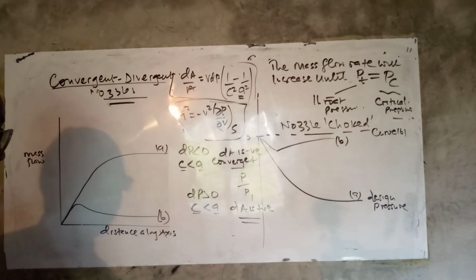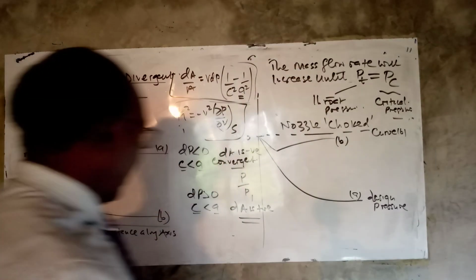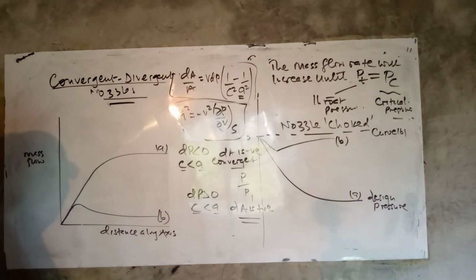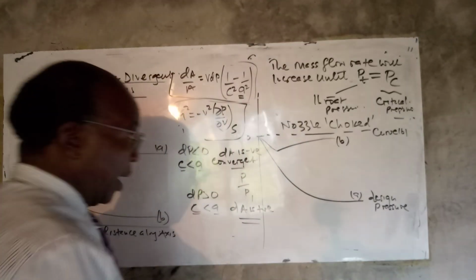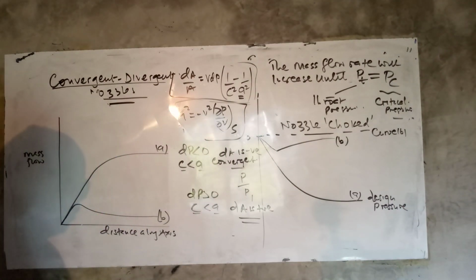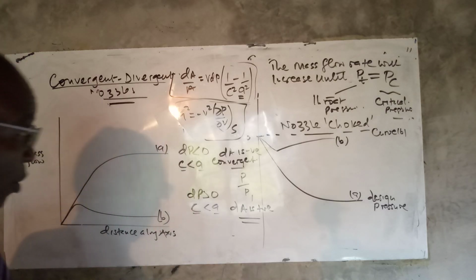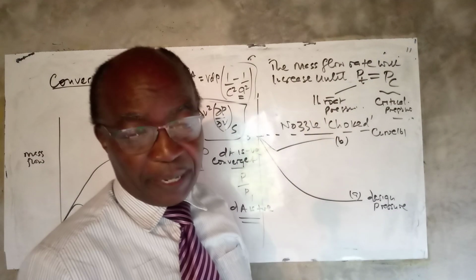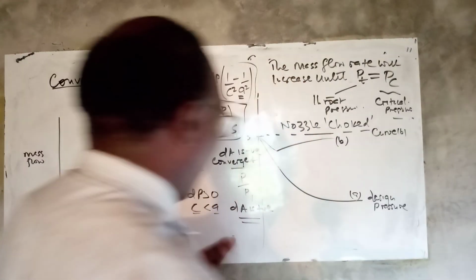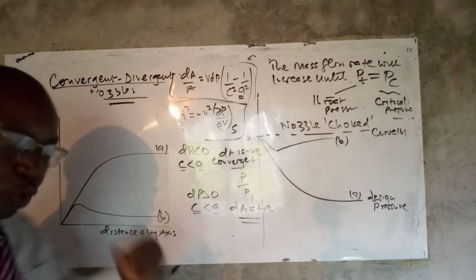Now, suppose we continue lowering the pressure, the downstream pressure. Of course, what will happen? Remember, once the throat pressure is equal to the critical pressure, there will be no change. So the nozzle is really choked. But what will be the situation?